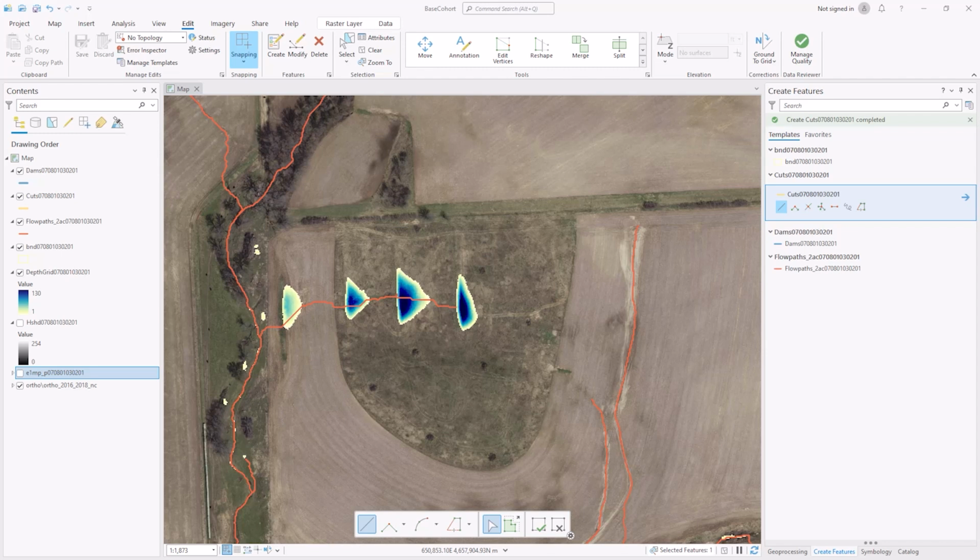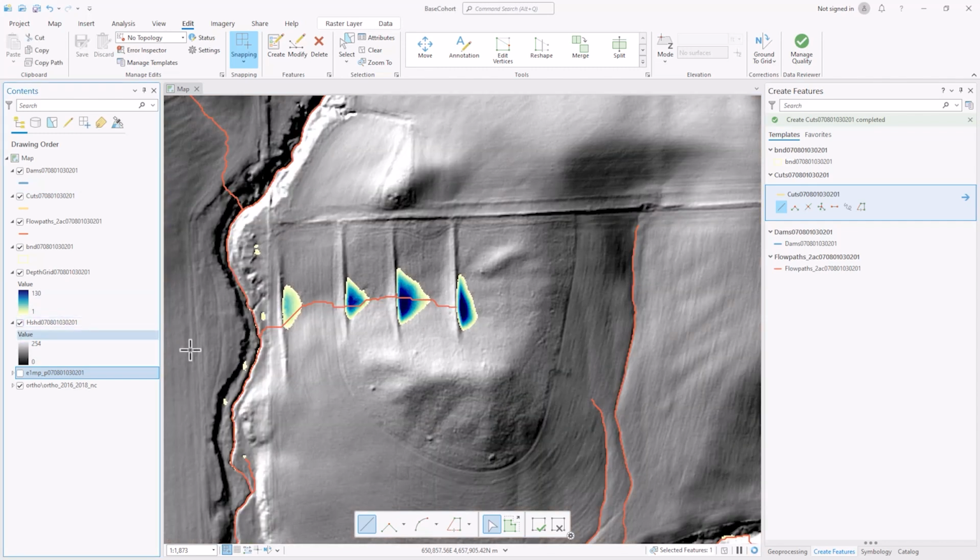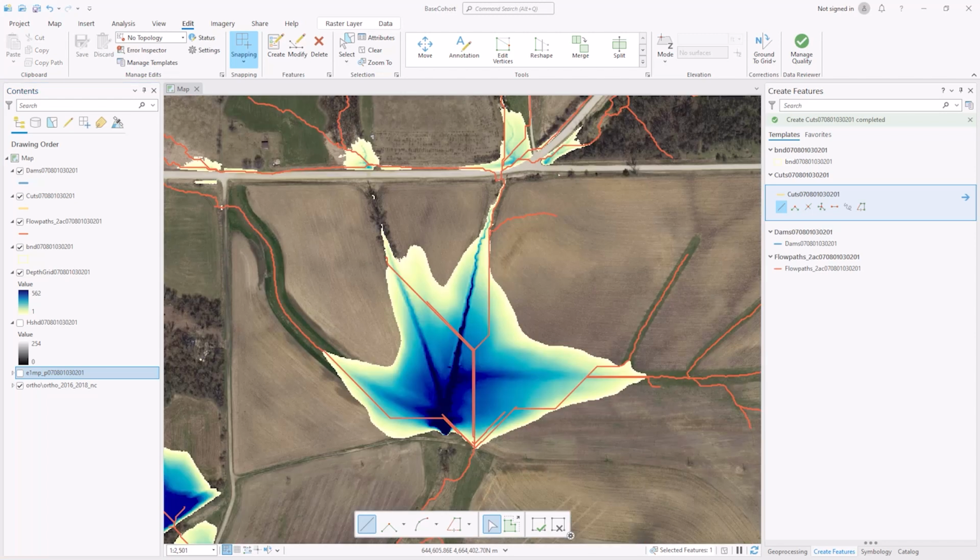There will be instances where we will find what appears to be an impediment. In this example, we have impeded flow with flat edges. Given that there is a series of impeded flow, if we look at the hillshade, we can see a set of wascobs have already been built in this field. Wascobs, terraces, and pond dams are cases where we will not place cuts as these structures are placed for flow management already.